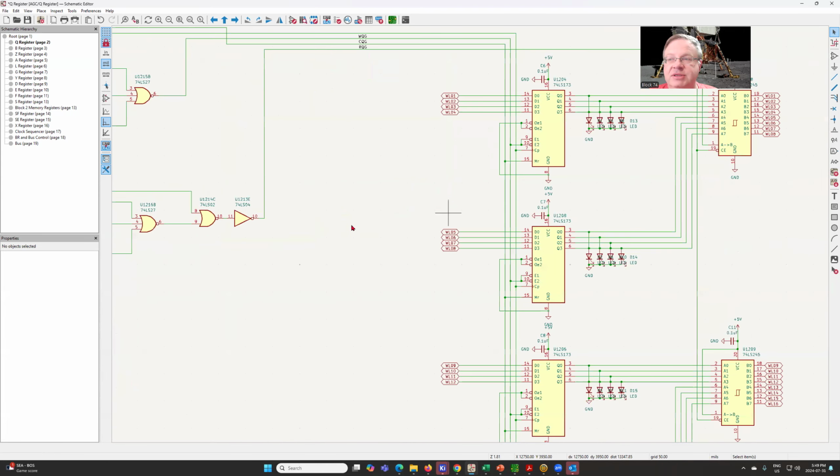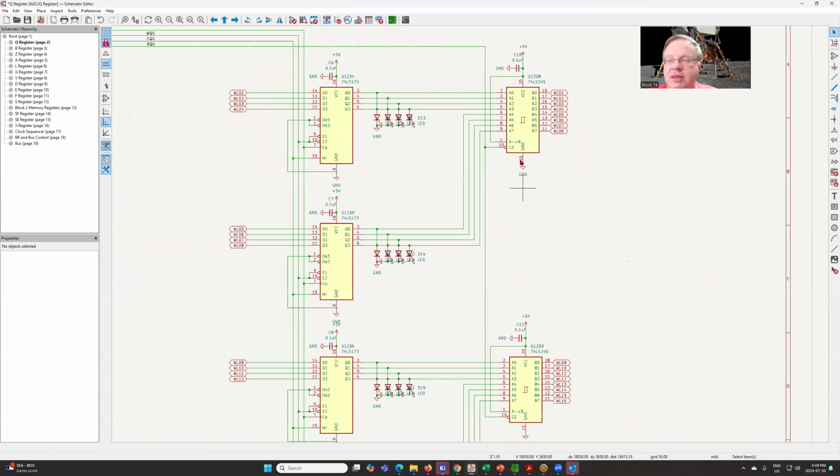So that means we're able to get rid of those 2-to-1 selectors. There were 4 of them, because each one is a quad 2-to-1 selector. And we're able to just bring the write line data directly into our registers. And then on the output side, we just read the data out onto the bus using our octal transceivers.